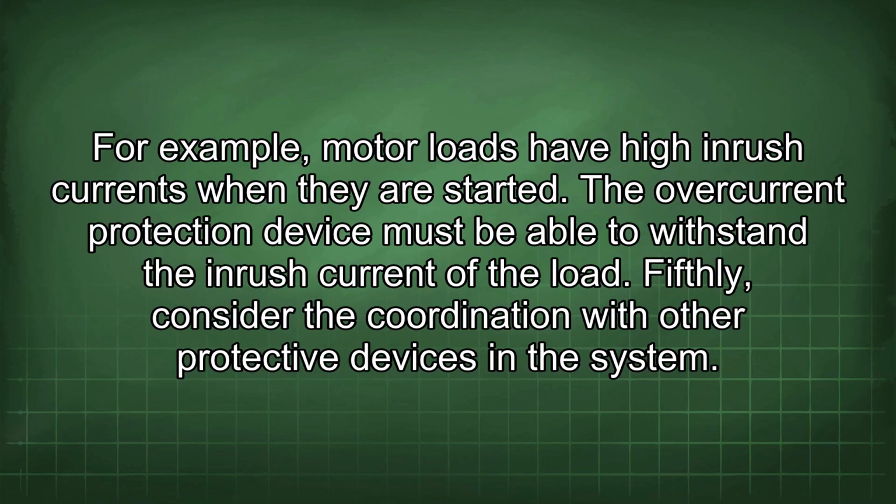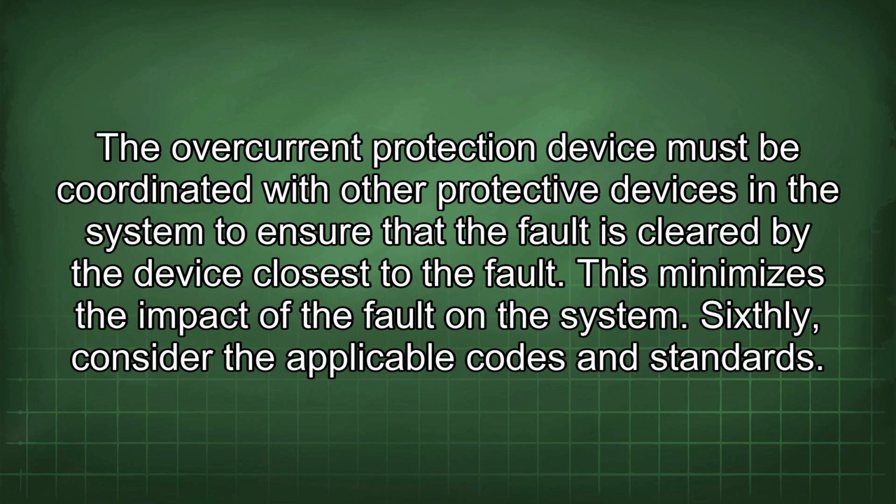Fifthly, consider the coordination with other protective devices in the system. The overcurrent protection device must be coordinated with other protective devices in the system to ensure that the fault is cleared by the device closest to the fault. This minimizes the impact of the fault on the system. Sixthly, consider the applicable codes and standards.